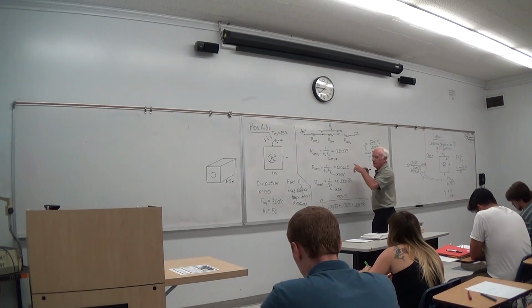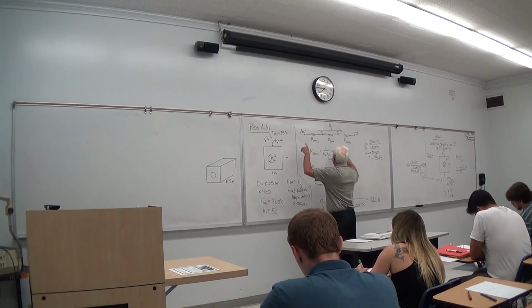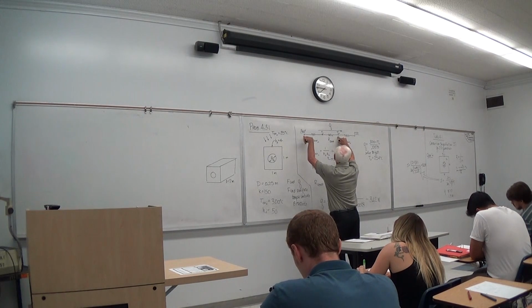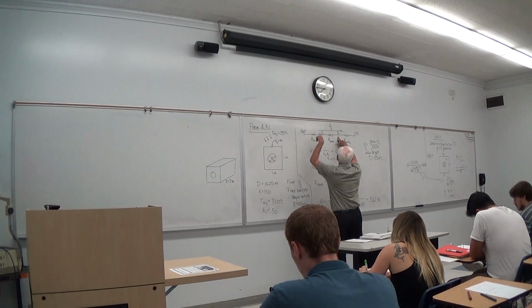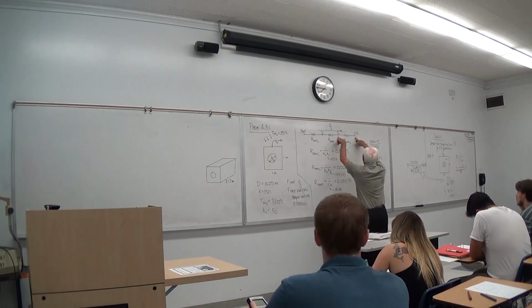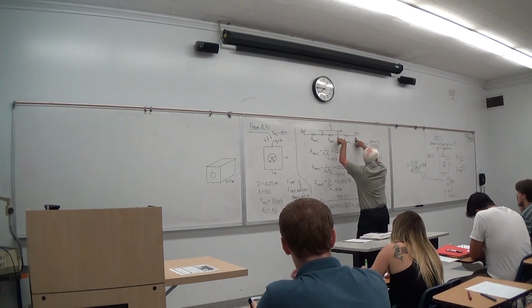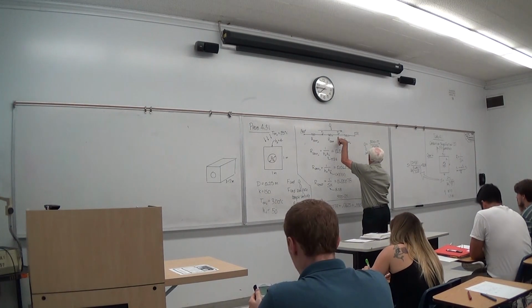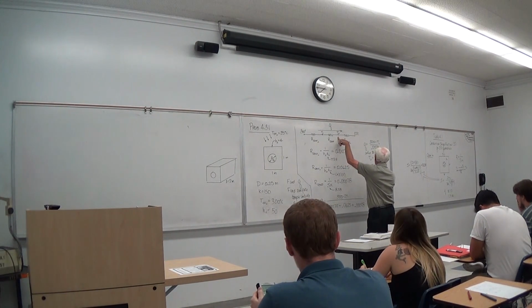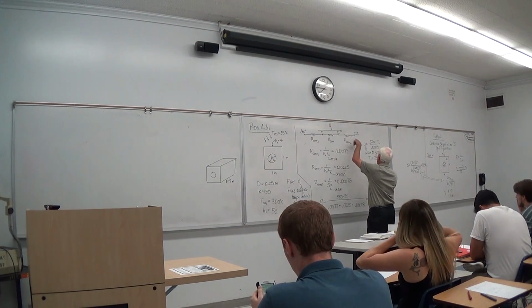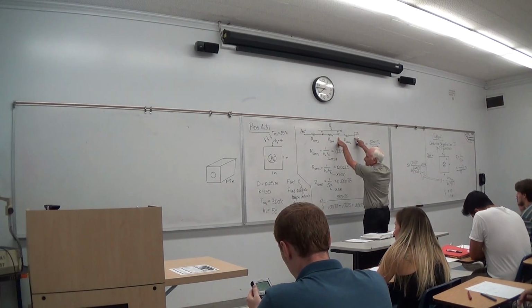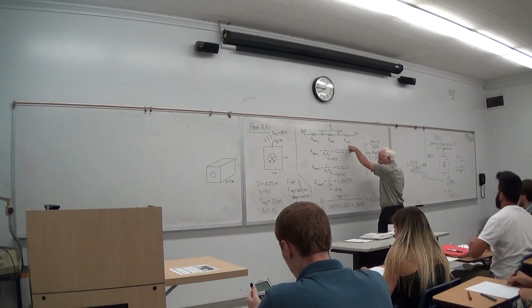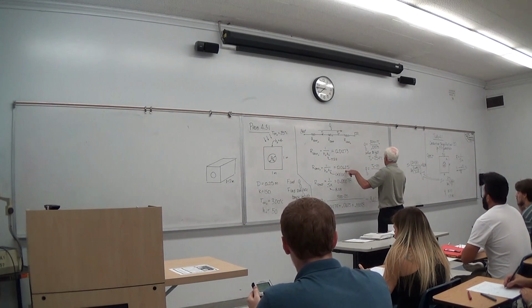If I want to get T on the outside surface, I can start at 300 and go to T outside, or if I want, I can start at T outside and go to 25. I'll go that way, a little bit easier. So Q equals hot temperature minus cold temperature divided by resistances between my two fingertips, or convection outside, 0.625.